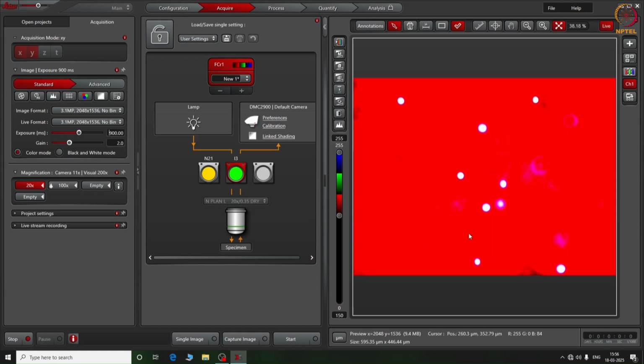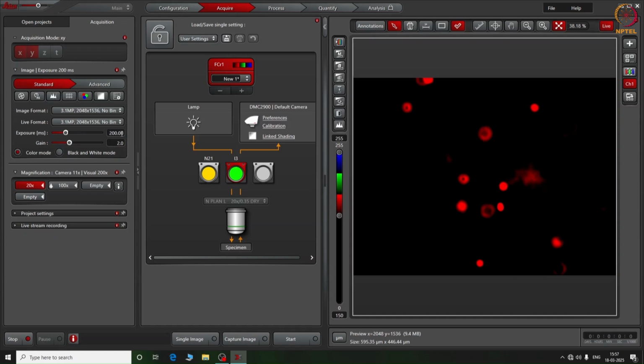we see these huge areas displayed in red. These are our saturated pixels, where the pixels are just overflowing with electrons. To fix this, we need to reduce our exposure time to get back within the range of the system. Alternatively, we can also reduce the number of photons entering the system to maintain optical image clarity.